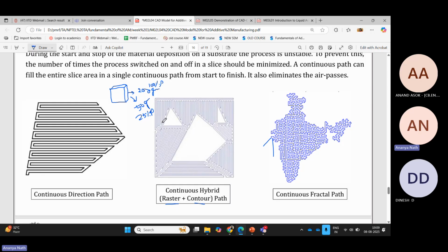So to make it lighter, you need topology optimization. Then if you are printing a cube in FDM process, then just to show the accuracy of the cube and everything, you do not have to print it with 100% density. You can put some gap inside the cube so that the cube will be lighter. So my benefit will be I will save material and I'll save cost. I will save time as well. So I am saving all three things together. So why not print less density cubes when my cube is not going to serve any purpose?